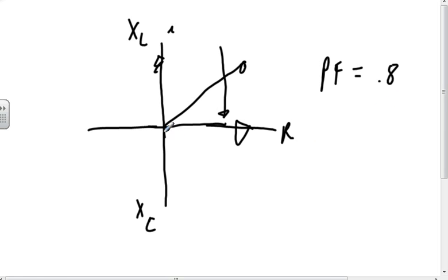But if I add a group of capacitors to the plant, normally in a room about a third of the size of this place, locked with a key because the voltages in there are too high, with a great big high voltage sign on it, then I can bring the power factor closer to one, and I can save a lot of electricity.